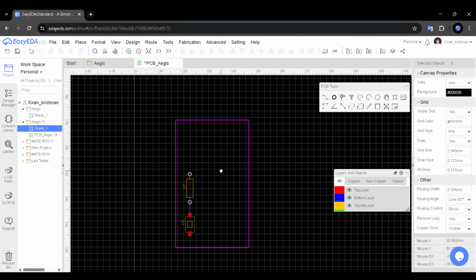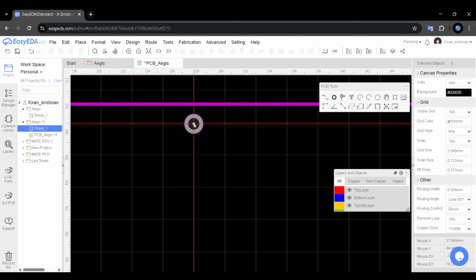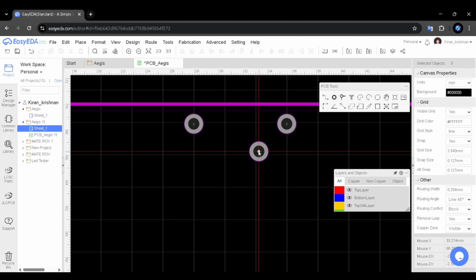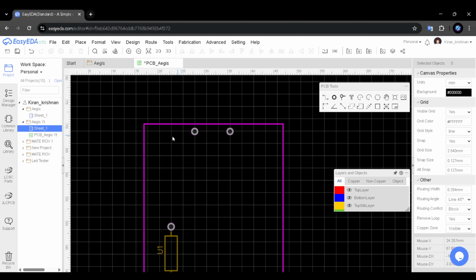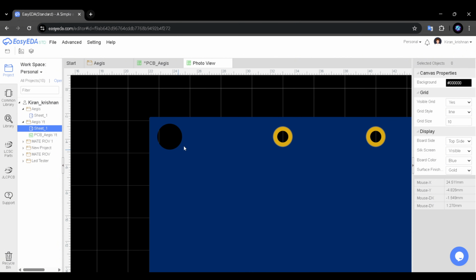And we'll add pads here. So these pads, what they do is basically they're going to have copper around them. So they're going to make it conductive. So a difference between a hole like this and this is basically, I'll show you right now. Okay. So there's no copper around it.